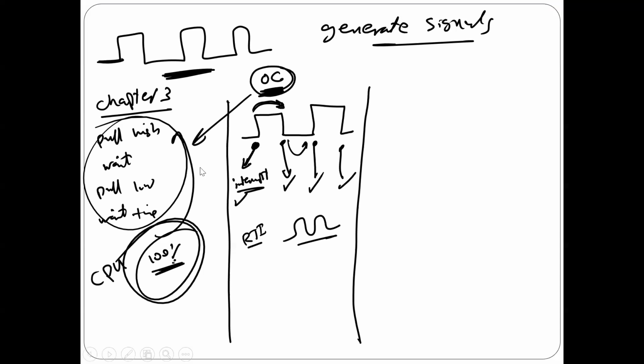Okay. So again, output compare is used if you want to generate a square wave this way, guys, efficiently, because I need only some time here for the interrupt, some time here for the interrupt, and this is similar to the idea when you used RTI to generate a square wave in test 2. Is that okay, guys? This is what output compare is. So output compare is used if you want to generate a square wave. Input capture is used if you want to measure time. Is that okay? The last thing we want to do, and it's really very, very interesting, is pulse width modulation.